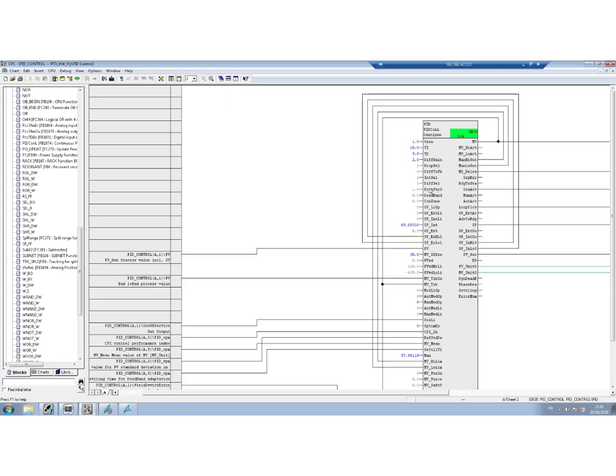This is the parameter B, right? And this one here is this Boolean parameter that allows you to switch from derivative action on the control error or derivative action on minus PV. Here you see also the deadband that we have encountered before.